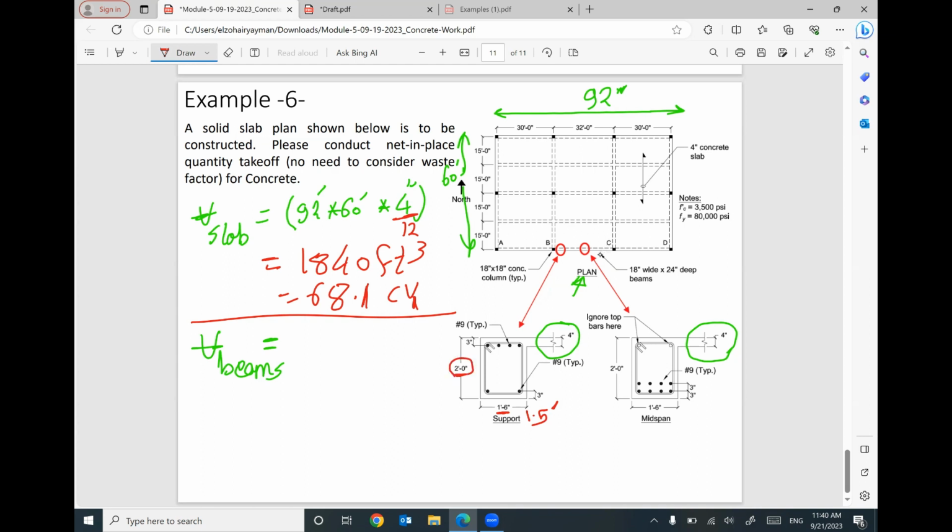We have a mistake here, because if you consider the cross section of your beam 1.5 times 2, there is a part here that will be counted 2 times. That means your calculation is not accurate, and you will order extra concrete. By the end of the construction, you will find much concrete still available, which is not good because more material means more cost, which is useless.